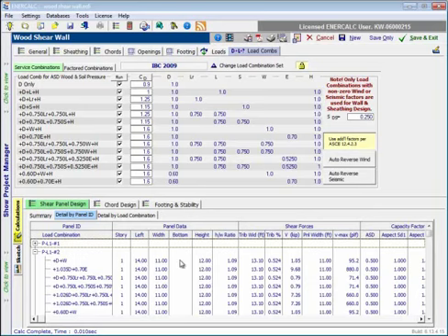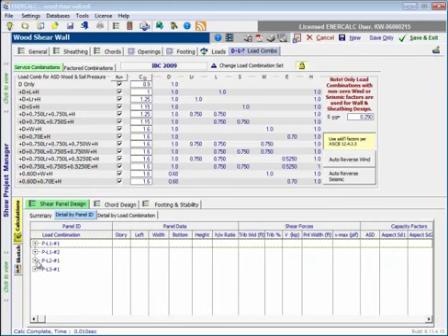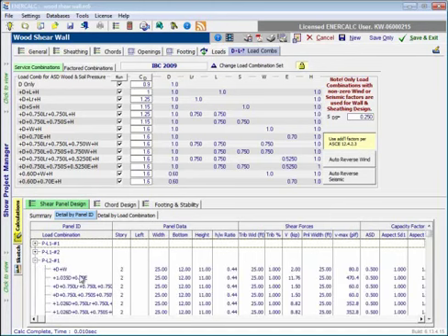The category called bottom is the dimension from the bottom of the wall to the bottom of the panel. So if we wanted to see a meaningful non-zero value there, we could come up to the panel at level 2, and here we can see that all panels at level 2 start 12 feet above the bottom of the wall. And then we see the height of the panel indicated. So story 2 is defined as being 11 feet tall, and we report the height to width ratio for the panel.